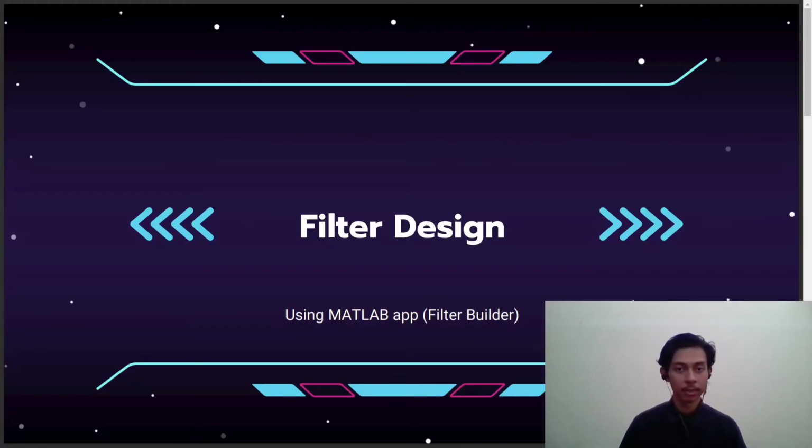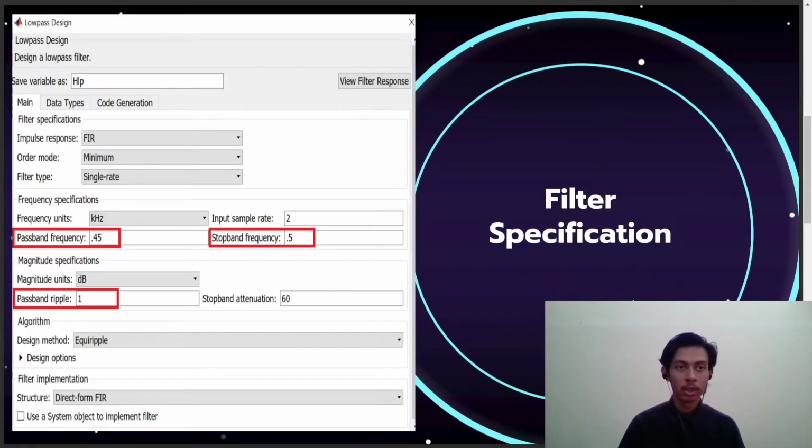Assalamualaikum and salam sejahtera. My name is Hafiz Syazani and I will be presenting on our filter design. We designed our filter as an FIR low pass filter using the MATLAB app called Filter Builder. From here you can see that our frequency specification is set to 450 Hz and 500 Hz.